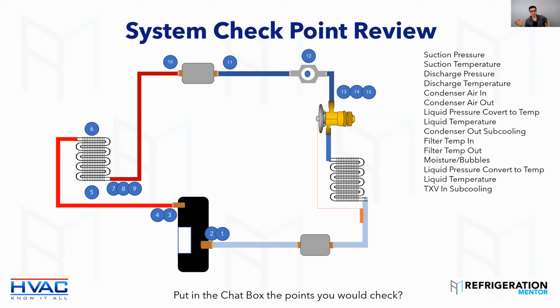And depending on the application, like if you're doing liquid injection for refrigeration low temp, it's great to have a sight glass to know if you got liquid going to those DTC valves or the TREV valves, temperature responsive valves. It's so important because you can look at it quickly and check it. Because sometimes, when it's just a pipe, you can't really measure across it to see if there's a temperature difference in certain areas, right? If you go from this side of the sight glass to this side, it's not going to be any different.